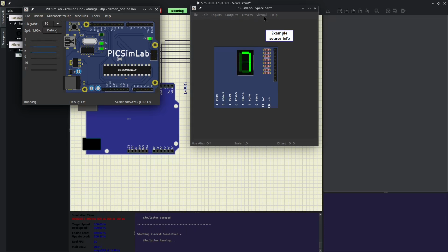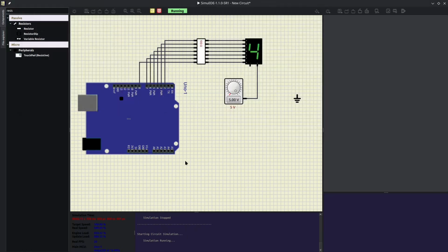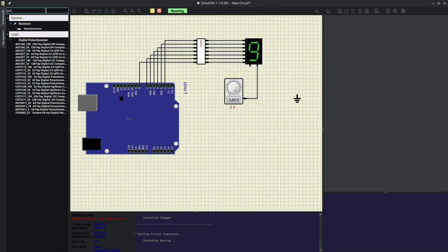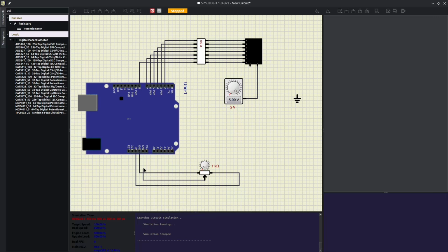That's nice. The last thing we need to do is make the workpiece with a potentiometer. Let's bring our potentiometer here and connect to our pins. We take this one and go to our VCC, and the other one goes to the ground. The GND and the other one go to the VCC, that is the 5 volts. And this will go to the analog pin.